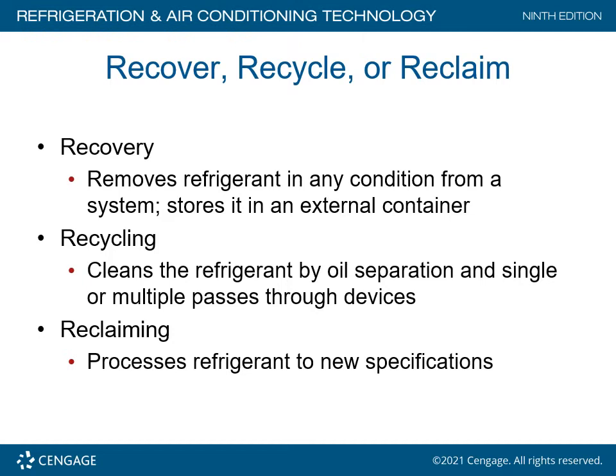Recover, recycle, or reclaim. You need to know the difference between the three of these. Recovery removes refrigerant in any condition from a system and stores it in an external container. Typically, when you go out on a job, whether it's refrigeration or air conditioning, you're going to pull out the charge of a system. As an example, you're going to do a change out from an R22 system to a 410A system, which I do all the time.